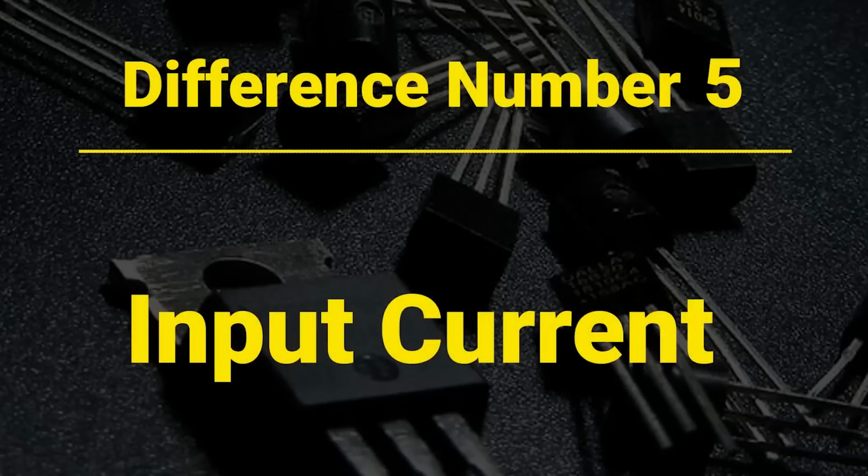The next difference is about the charge current. Difference number 5, input current. We all know that once the input capacitors of a MOSFET are charged, there will be no need for extra charge or current to keep the transistor on. Actually, the current flowing to the gate terminal will be 0.